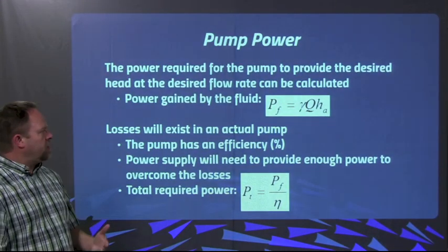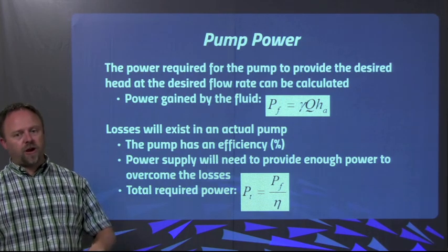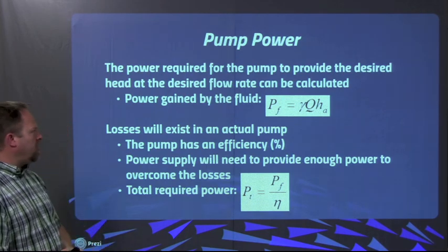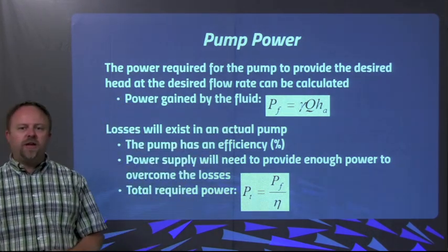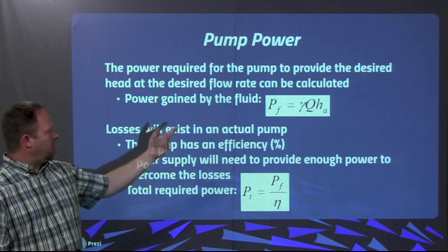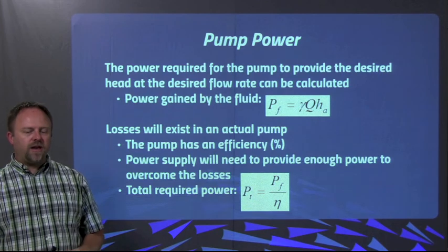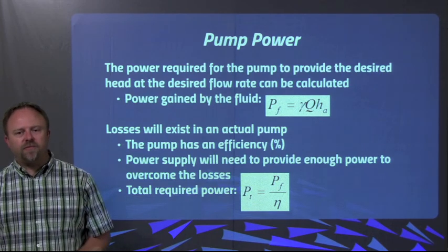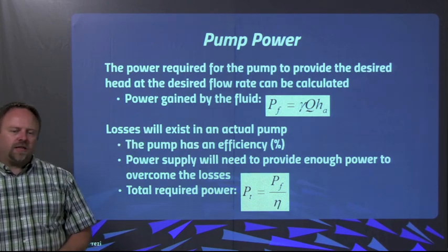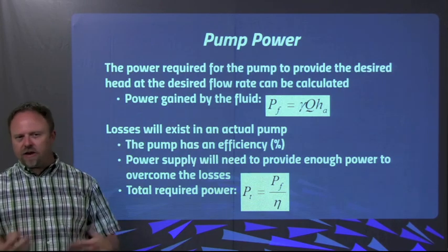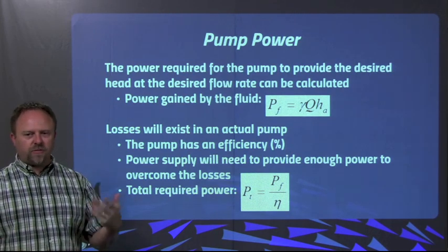And in order to determine how much power our pump is going to need, we have to provide a power supply for our pump. We need to figure out how much power we're going to need. We can find out how much power is induced into the fluid by the pump from an equation, which is the specific weight of water times the flow rate times the head that we're getting from that pump. And there are going to be losses too in the pump itself, due to some mechanical movements going on and the water flowing inside the pump. There's some losses that occur.